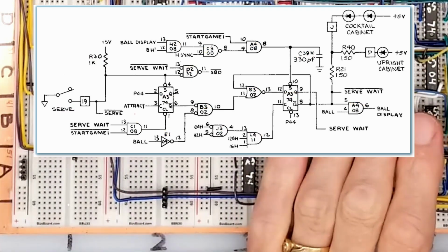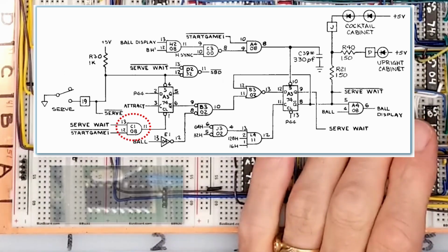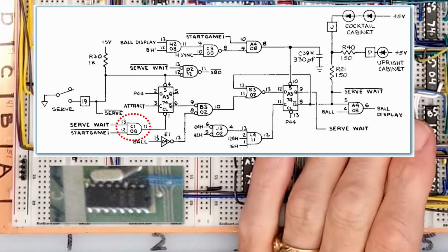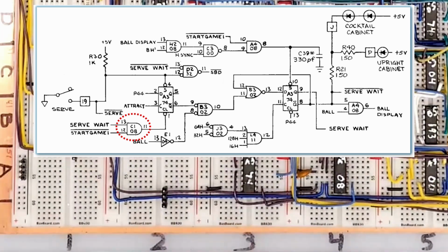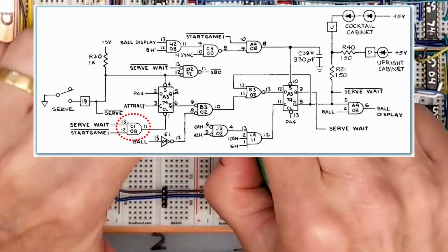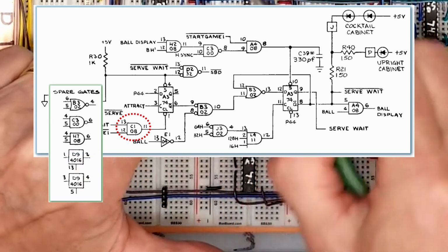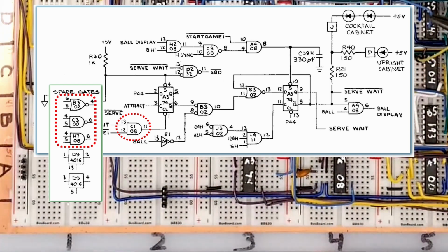Here we finally find that elusive 7408 in Charlie 1. This chip was added to the boards in an engineering change between Revs C and D, but you won't find any gates from Charlie 1 in the Rev F schematics in the manual. They evidently needed another gate here, not realizing they had some spares laying around from previous changes, because the schematics were not kept up to date.